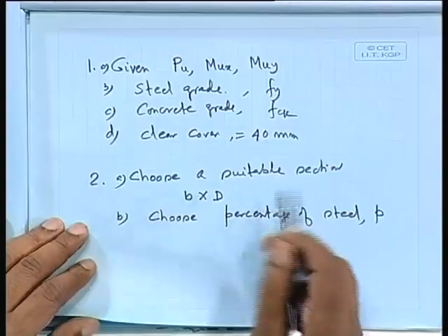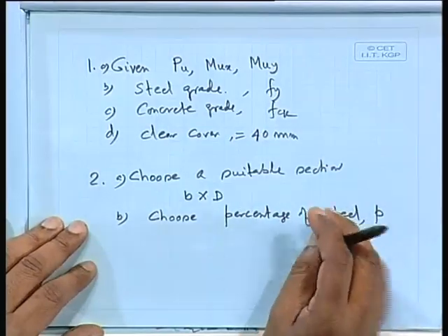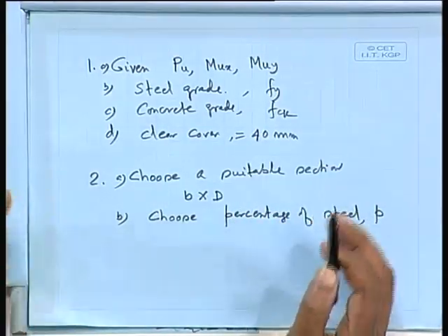Here in this case you can say as if you are doing the analysis rather than design, compared to, say, a beam or slab, where you are providing the section, calculating the effective depth and then providing a section. But in column design, analogous to that, I am doing the analysis part. That means I am taking all the things and checking whether my trial section is correct or not, whether it is safe or not. That is what I am trying to do.